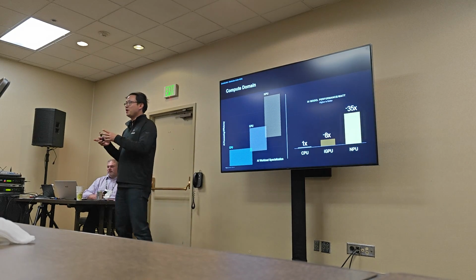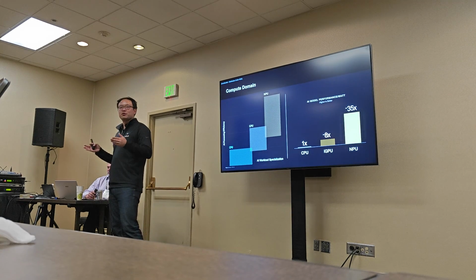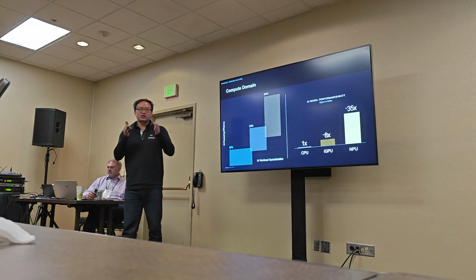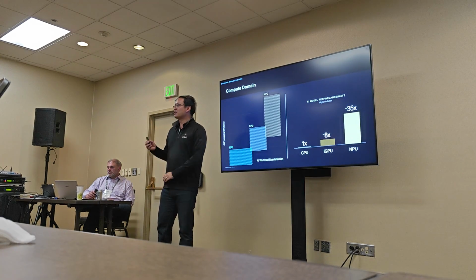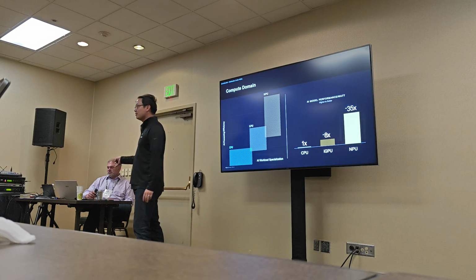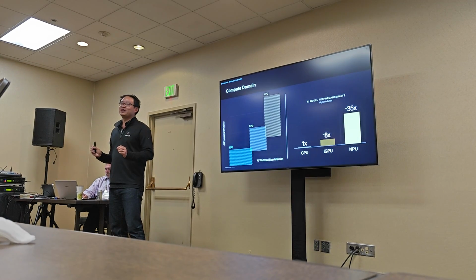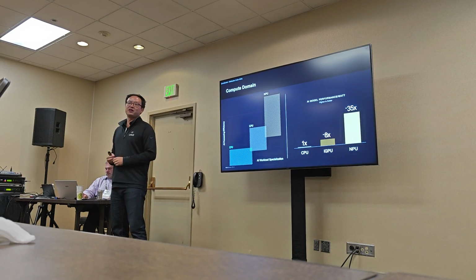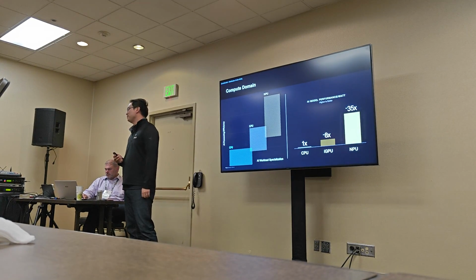Because it is an optimized architecture for these kinds of neural networks, while it has only a narrower span or workload coverage. But once you fit into the nice workloads, you're gaining a huge amount of power efficiency, which is super important, especially for Copilot PCs, where a lot of these workloads will be running all the time, right? So you don't want that to drain your battery. So you want to move those heavy-duty tasks to the NPU as much as possible.